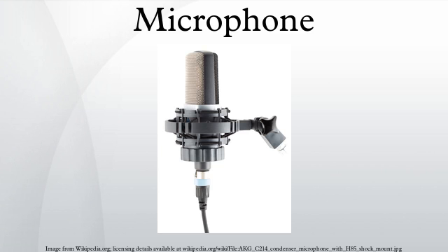Note that the time constant of an RC circuit equals the product of the resistance and capacitance. Within the time frame of the capacitance change, the charge is practically constant and the voltage across the capacitor changes instantaneously to reflect the change in capacitance. The voltage across the capacitor varies above and below the bias voltage. The voltage difference between the bias and the capacitor is seen across the series resistor.